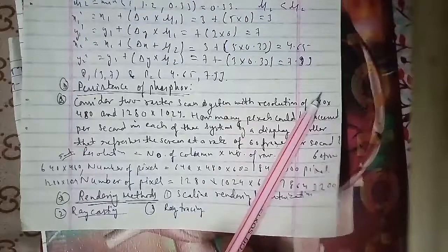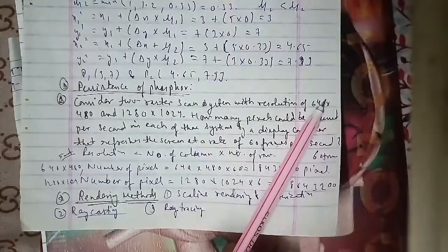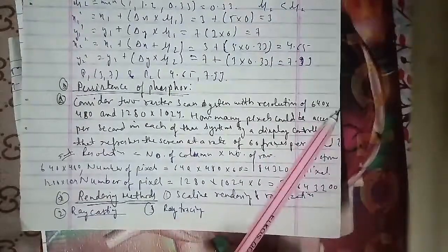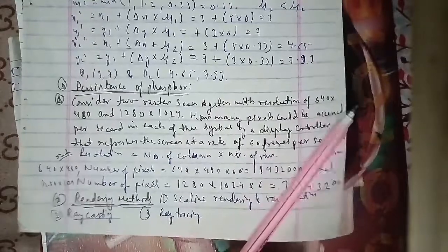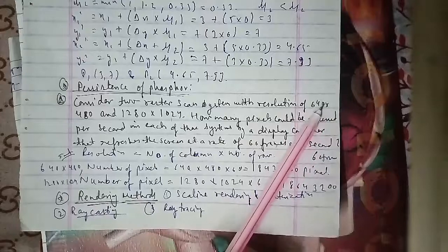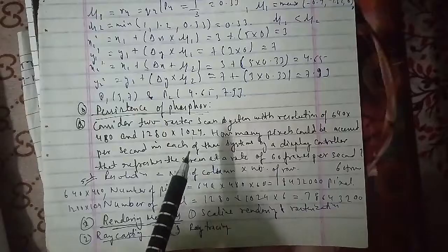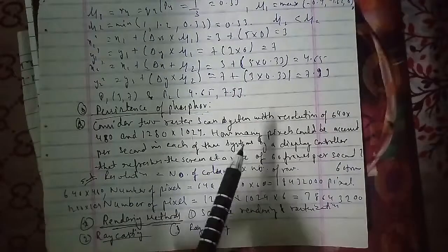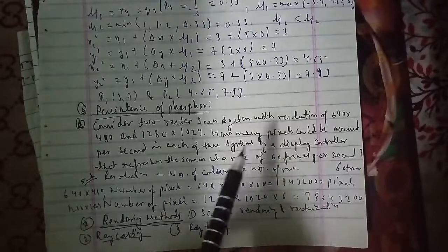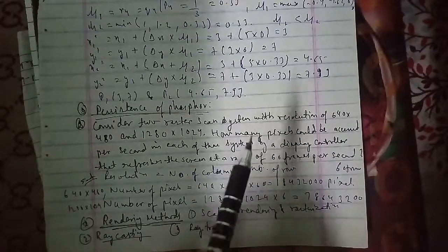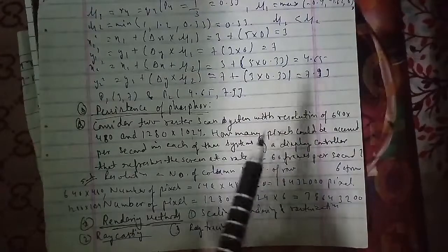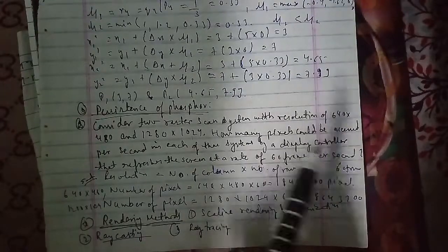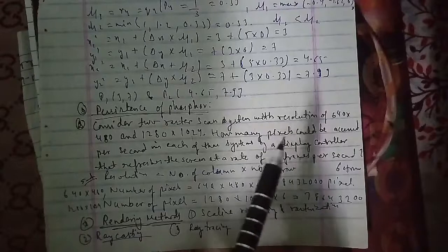Then after that we have one question here, that is the differences between the B-spline, Bezier and spline, which we have to discuss here. So the last question: B-spline curves are specified by a Bernstein basis function that has limited flexibility. In Bezier, the curve can be specified with boundary conditions, without characterizing the matrix, or with a blending function. In spline, the spline curve can be specified by a given set of coordinate positions called the control points, which indicate the general shape of the curve.